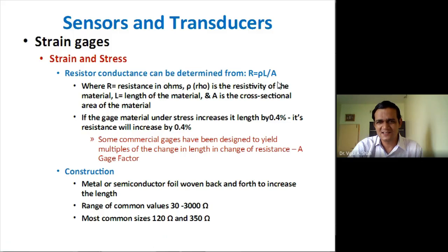So resistance can be measured in terms of this, and if you keep this strain gauge in the Wheatstone bridge, you can monitor and maintain this resistance through the Wheatstone bridge circuit. So effectively you can measure the stress and strain which is occurring in muscle expansion, contraction, etc. So all muscular activity you can monitor and control using the strain gauge utilized for this particular purpose.